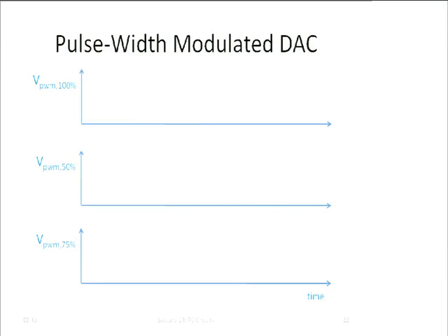Well, what does a microcontroller do well? Basically it has a whole bunch of outputs, and all of these outputs, they can be either 0 volts or they can be VDD. These are digital outputs. And of course, we can use a program to tell them, now you be 0 and now you be VDD, right? And we can change that very rapidly all the time. Okay? So how could we use that for a digital analog converter?